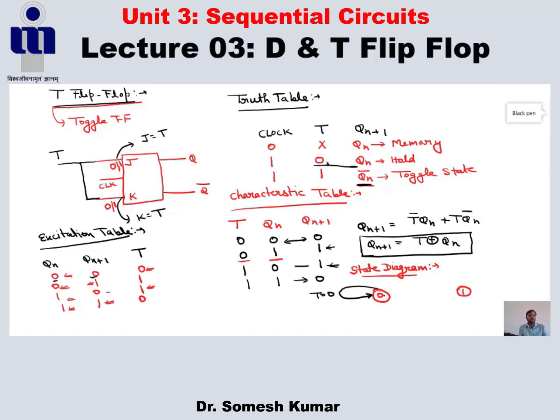If the previous state is 0 and the next state is 1, T equals 1. If the previous state is 1 and the next state is 0, this happens when T equals 1. When Qn is 1, previous state is 1, and Qn plus 1, next state, is 1, it happens when T equals 0. So this is the state diagram of our T flip-flop.